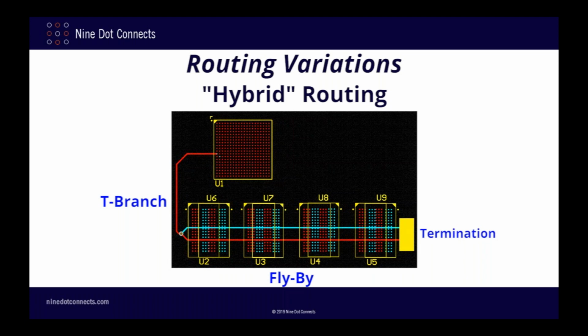I brought this hybrid concept up to reinforce the fact that you're not necessarily constrained to one specific routing paradigm for DDR3 layouts. As long as you end up with acceptable timing results and levels of signal integrity, you are free to do whatever you need to do in order to get your design and layout to work.